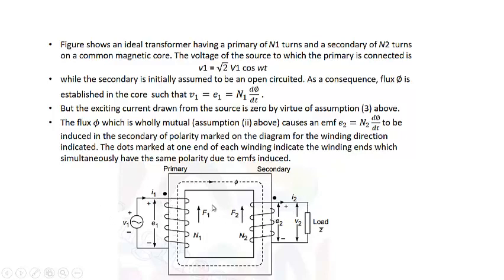There will be only current that is balancing this current. Because I will repeat again, when this current increases, the MMF produced by this winding, that is N2 I2, will produce a flux which will be opposing to this flux. This flux reduces, which reduces this flux. When this flux reduces, there will be imbalance between V1 and E1. I1 will increase in such a way so that it increases the flux.